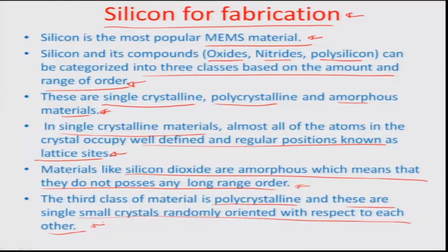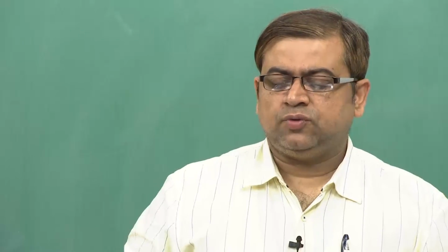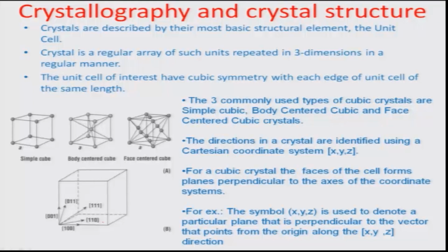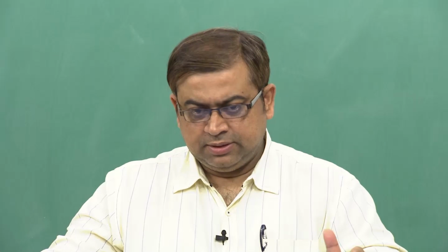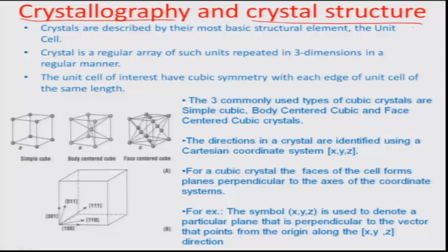Almost all of you who have done my course on the first part of manufacturing technology have probably gone through all this, and how crystal formation takes place, what kind of defects there are in crystals, and so on. Here we will focus on a slightly different aspect, which is how the crystal structure of silicon can be envisioned and represented, and then how you can play around by introducing chemical machining like etching processes, or physico-chemical etching processes, or only a chemical or a physical etching process through a beam. Therefore we need to study the crystallography and some crystal structure aspects of silicon.